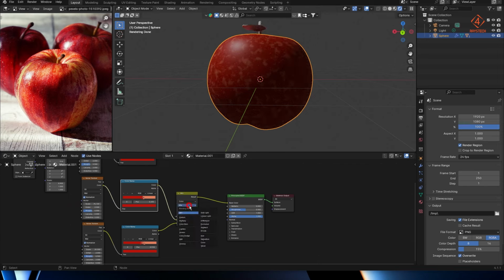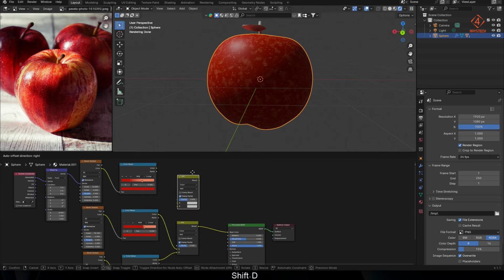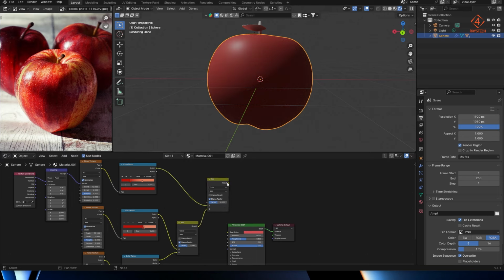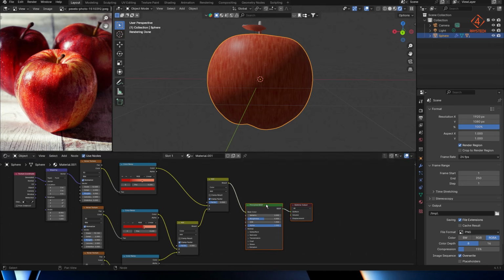We'll be using this result now to add with the vertical lines that we've created above. So let's just finalize this by using the mode add. And as I said before, we'll be adjusting this every now and then when we come back. This is a creative process, so that's how it goes. And using the same node, Shift D to connect it with the previous input, and now connect it with the vertical noise. Connect it to the final base color, and there you have it. So I will switch the mix mode from add to mix for a final result. Yeah, and I think we'll just use some adjustments here and there.